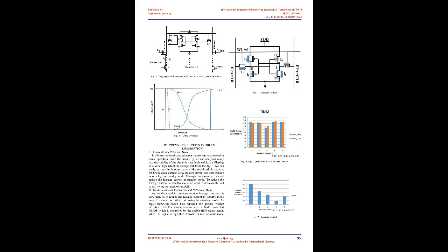See write operation. In figure 4 the write operation of memory is shown. For write operation, pull the bit line or bit line bar to 0V through the write driver pulse, which is controlled by the write signals WR and WRB, and now put the word line, WL, from low to high, 0 to VDD. The bit line starts to discharge and tries to pull down node 1 via the pass gate. At the same time the pull up, PU, transistor tries to pull it up through the pull up and pass gate transistor. We make a powerful write driver and pass gate, which avoids the condition of flipping.